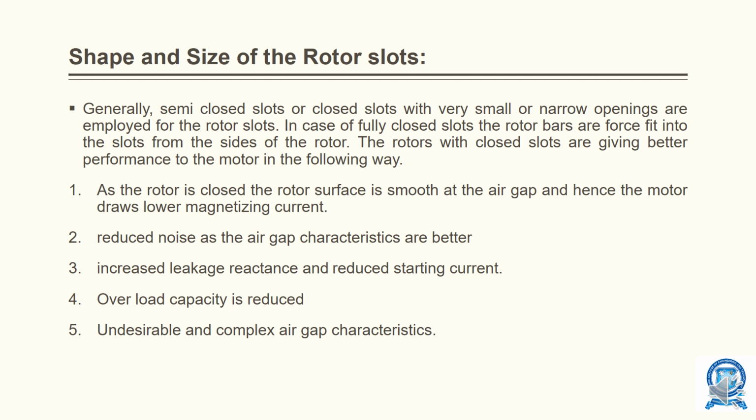Size and shape of rotor slots. Generally, semi-closed slots or closed slots with very small or narrow openings are employed for rotor slots. In case of fully closed slots, the rotor bars are force fitted into the slots from the sides of rotor. The rotor with closed slots gives better performance to motor in the following ways.